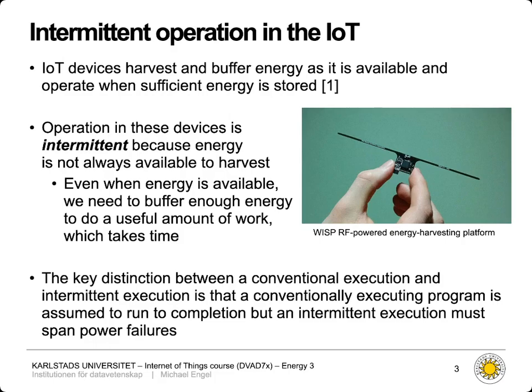Now, there are also several physical reasons for not directly powering a device from an intermittent energy source, and this might be mostly related to the voltage and current supply characteristics of a semiconductor chip. Very often the voltage and the current supplied by an energy harvesting device are not really directly compatible with what our semiconductor needs. So a storage element in between, like a capacitor, as we've seen, or a small battery, can help to alleviate these differences by adapting the voltage and the current as needed.